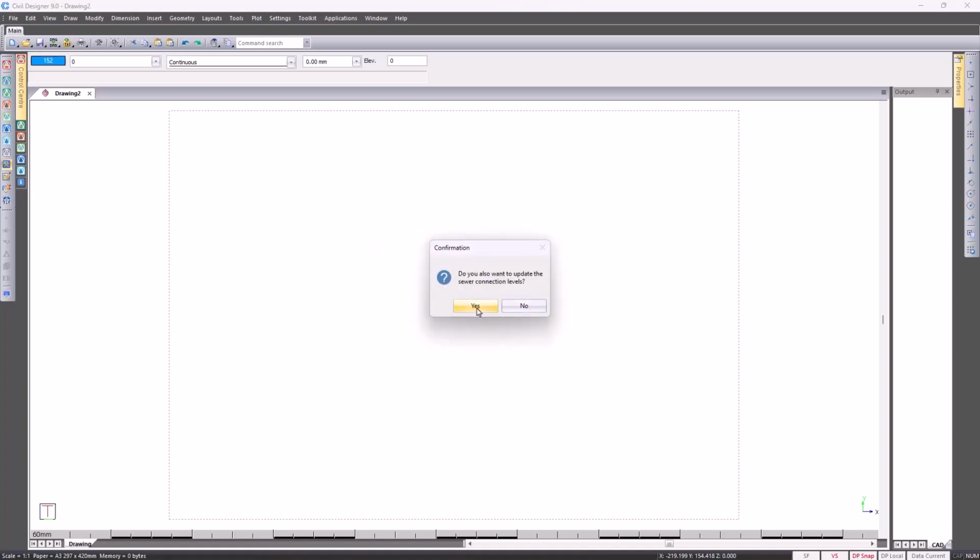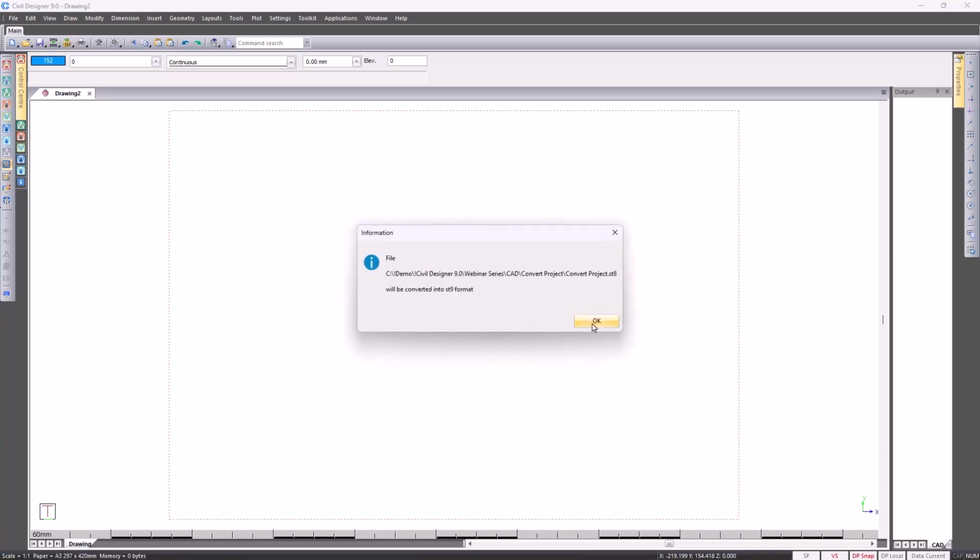As before, this message is due to the renaming of the DTM from a DT8 to a DT9 file. The same applies to the stormwater files, being upgraded from an ST8 format to an ST9 format. In this process, all associated files are moved into the ST9, such as the defaults file, hydrographs, pumps, and reservoir files.